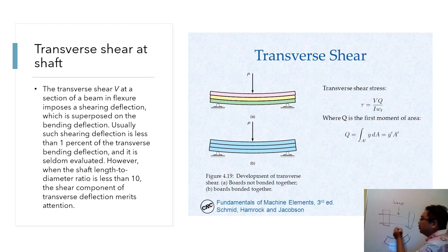Because of the shear effect. This is a shear. This is the point that you clamp. So what is allowable shear? This is only allowable 1% of the deflection. If beyond 1%, you have to redesign. Maybe you have to increase your diameter, and also maybe make the clamp shorter instead of longer. Maybe you can change the material property of the shaft and everything.